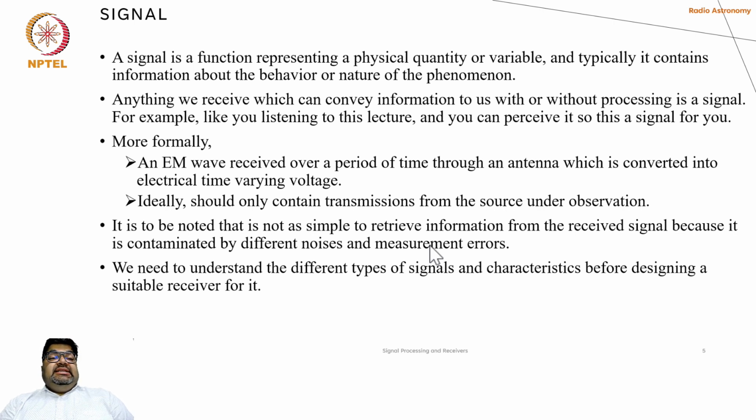So, like I said, there are radio frequency interferences. We are collecting at a particular band, for example, say 1.4 gigahertz. But there can be spurious transmissions nearby, in the nearby frequencies, which can spill over because of non-ideal or imperfect transmission modes, and they create noise for our reception.